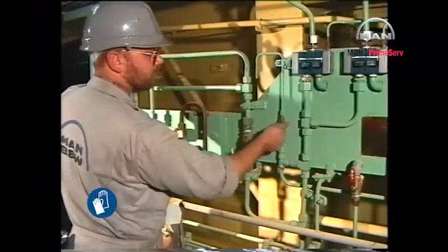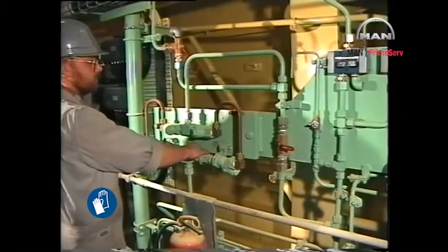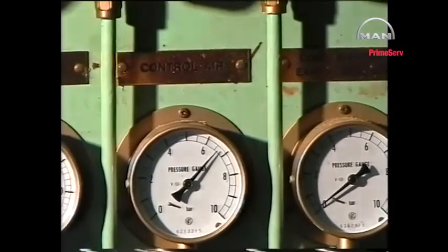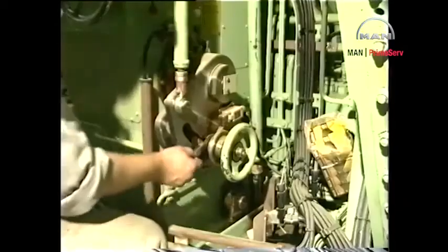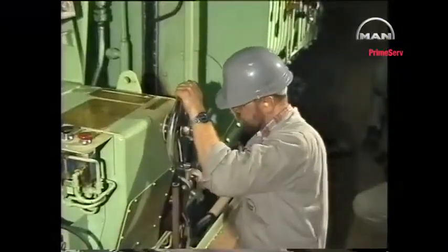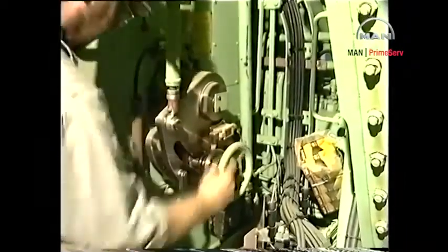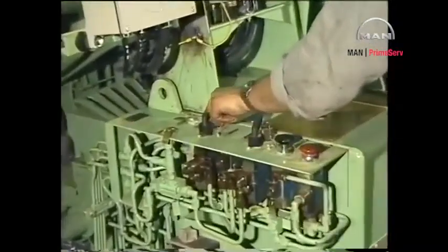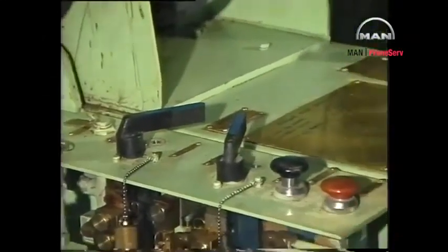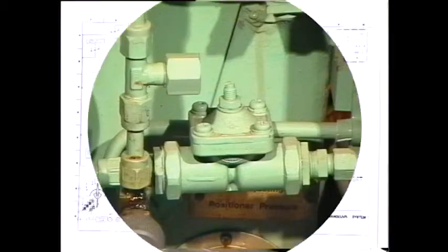Supply 7 bar control air pressure to the pneumatic components on the engine side console. Switch control from the engine room to the engine side console. Turn the regulating hand wheel until the tapered slots of the 2 levers are aligned. The throttle non-return valve must be fully open before adjusting the VIT system.